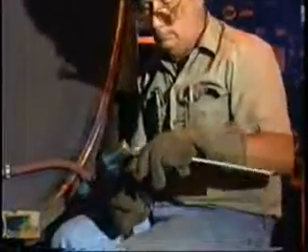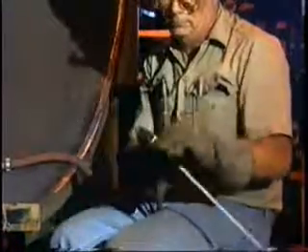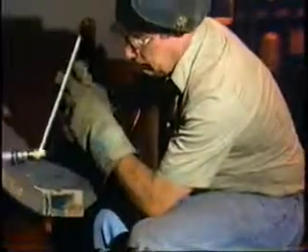The bare section of the electrode is clamped in a holder which is connected by a welding lead or cable to a terminal of a constant current power source. The workpiece is connected to the other power source terminal. Touching the tip of the electrode against the workpiece and withdrawing it slightly initiates or strikes the arc.